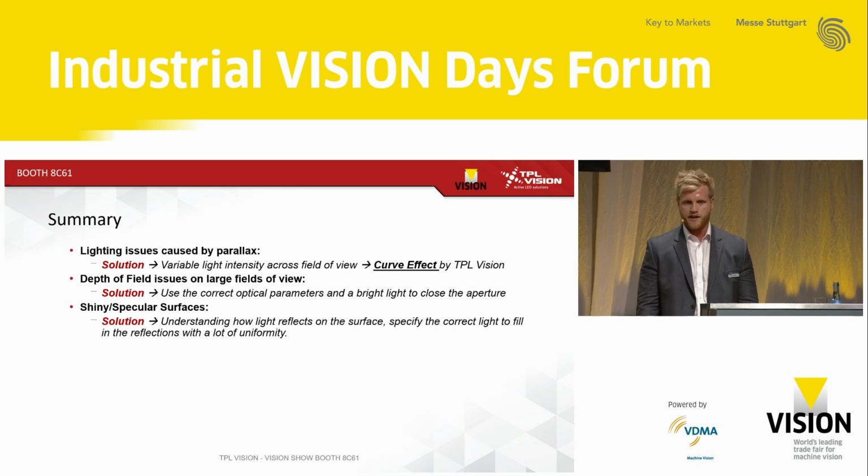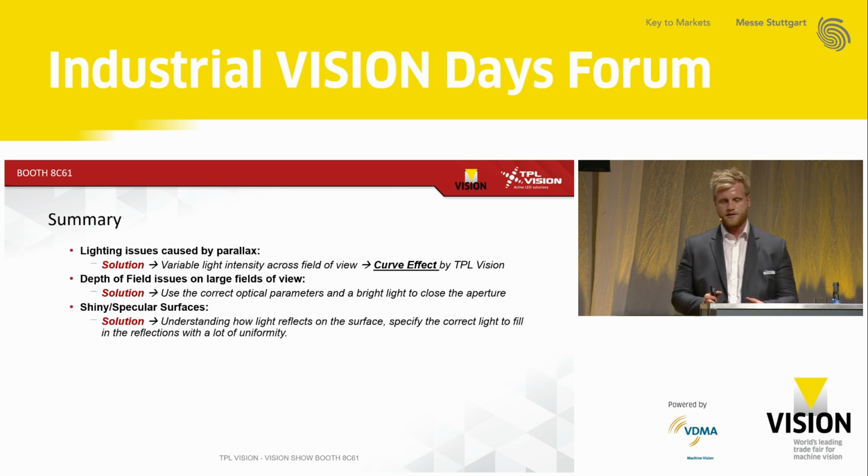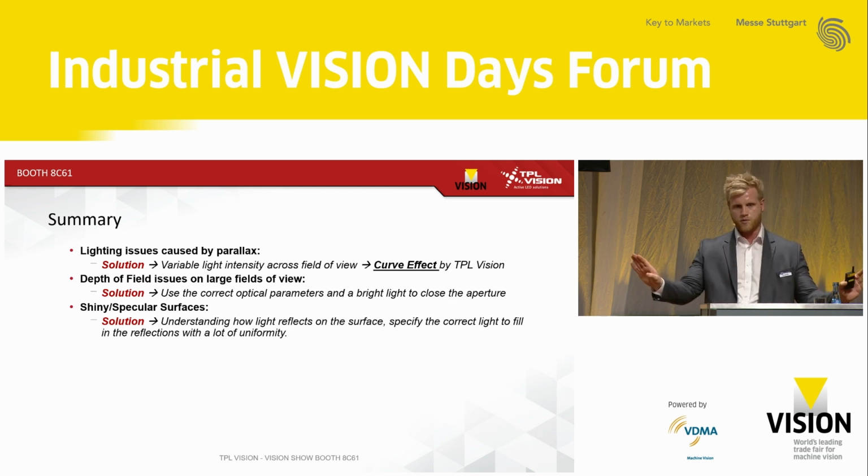So when you're looking at shiny surfaces, actually the smaller the radius is, the harder it is to see. And that's because if you imagine you're following what the light sees in the reflection, when you have a really, really small radius, as soon as the camera looks at the part, what the camera sees goes wide. So you need to really fill the entire area with light.